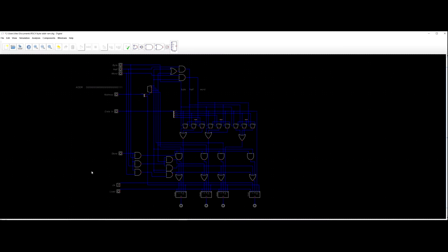So when you produce a circuit board, you want to test it to make sure that the circuit board you built is going to work. You're not really testing the logic inside at that point. You're testing, is it soldered correctly? Is there shorts and stuff like that? If I send out this bit, is there 3 bits on at the output? Is there a short somewhere? It's more like at the board level there.